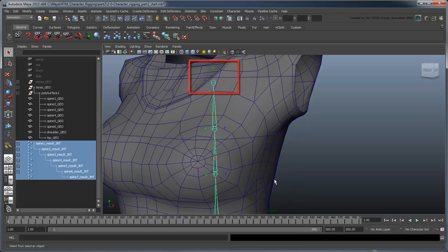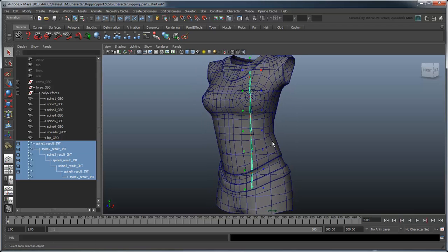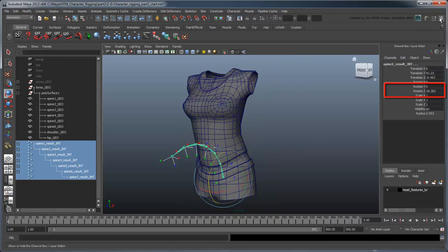However, since this is the end of our joint chain, we don't actually need to worry about it since its rotation won't be affecting anything. If you rotate the entire chain once more around the y or z axes, you'll get a uniform rotation. Notice how a positive rotation bends the chain forward? We typically want the positive direction to be the most common bend direction.